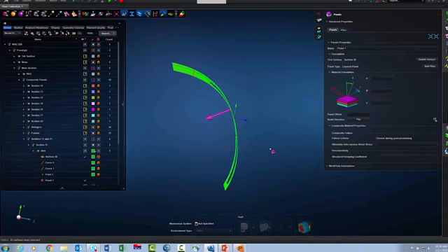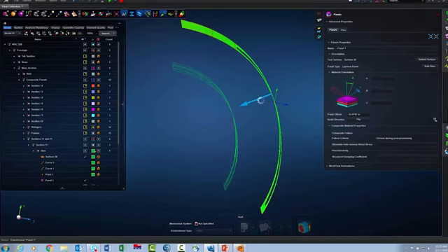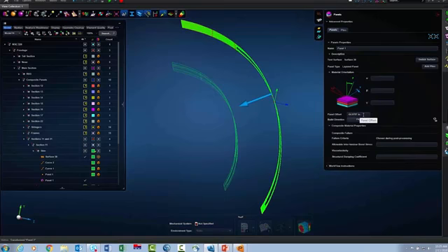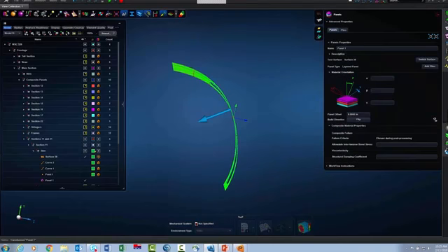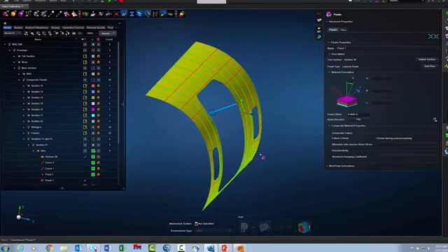If my geometric surface didn't actually represent the tooling surface, and I wanted to be particular about my offsets, I can come in here and reset the panel to the proper offset position for the tooling surface. Here I've done something very exaggerated so we can visually see it, but you can also type in a number if you know what the offset is. I'm going to go back to 0 here because my geometric surface really does represent the outer mold line and where the tooling surface is.